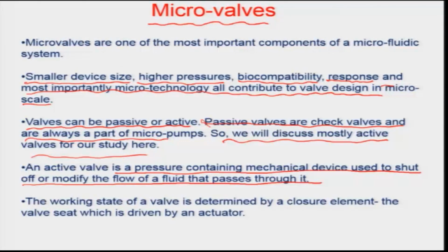In this kind of circumstance, typically the working state of a valve depends on the position of the closure element, and the valve seat, which is actually the closure element, is driven through an actuator of some sort, based on a variety of physical principles. We are going to look into the design aspects of two such principles. One is the pneumatic design, and another is a thermopneumatic design of an actuator which would contribute to microvalving of the flows at that particular length scale.